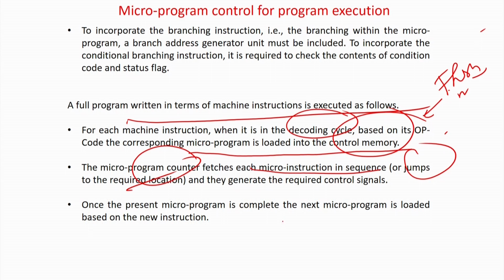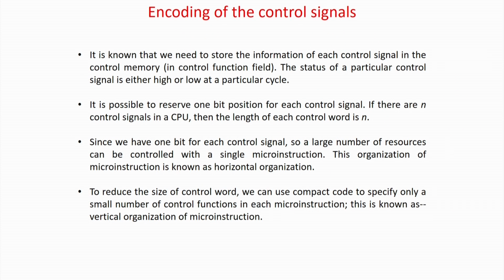Once the microprogram is completed, the next microprogram is loaded based on the new instruction, that is very important. So, when add has been done and is complete, the MPC will again start pointing to the fetch part, which corresponds to the new macro instruction. Okay.